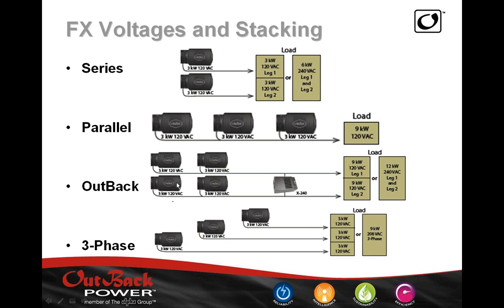The next stacking is essentially a combination of the 2 on top here, series and parallel, where you can have up to 5 inverters per phase for a total of 10. The XW240 here that we see is basically a transformer that allows us to balance the phases so that we're not going to overload the neutrals, and we'll talk more about that.